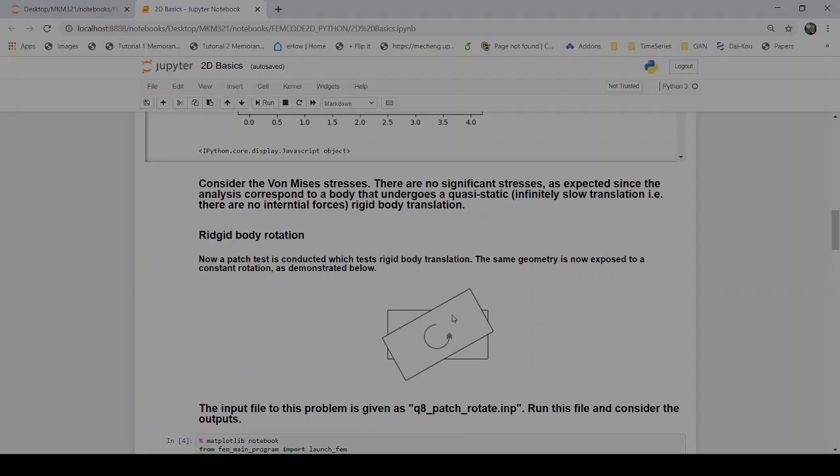What's my expectation from the solid mechanics point of view for my theory? Because remember, we do linear elasticity. When we had angles, did we do any simplification with them at any point? Yes, we did. We made all those angles, the tangents, cosines and sines, we simplified all of them and linearized them.